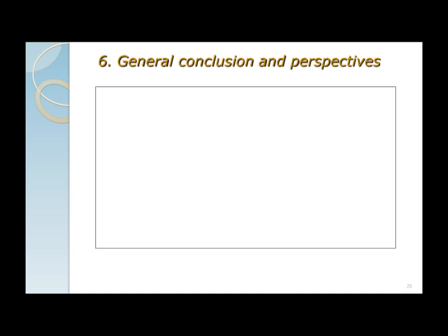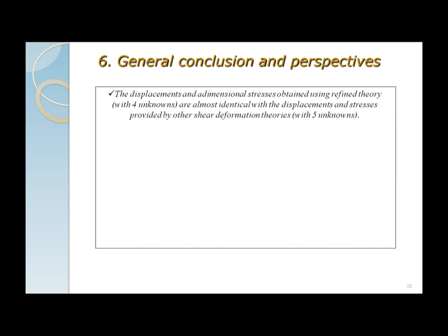General conclusion and perspective: the displacement and non-dimensional stress obtained using the refined theory are almost identical, while the displacement and stress provided by other shear deformation theories differ. The deflection is maximum for a metal plate and minimum for a ceramic plate.